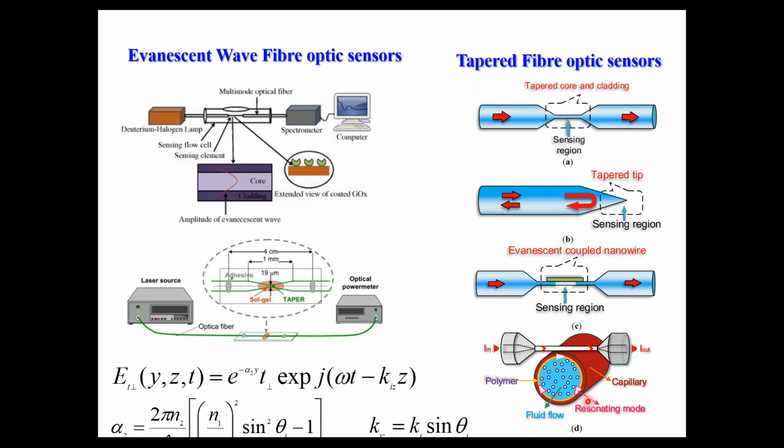This kind of sensing we have already discussed in the first session. You have a fiber that contains the light, and this is the in and this is the out, and in between it is tapered, and in the tapered region a micro cavity is placed. So some frequencies can be coupled into the microsphere or micro cavity or micro cylinder, whatever shape. The spectrometer analysis of the output will show that certain frequencies are missing. In that way also the evanescent field plays a huge role in all kinds of fiber sensors.